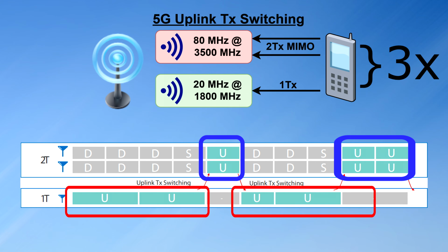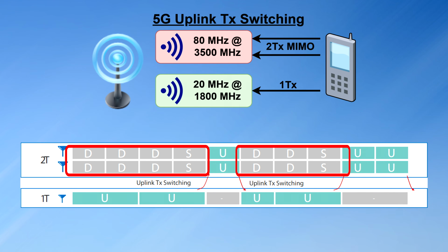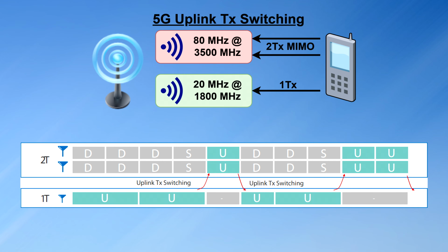single transmit antenna. The trick is to take advantage of the time division duplexing of the 3.5 GHz high band, while occupying the downlink time domain of the TDD band by sending data over the FDD band instead. Of course, the handset requires the necessary hardware-based components like antenna modules, filters, transceivers, etc. to take advantage of this feature.